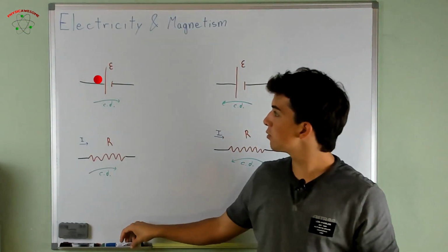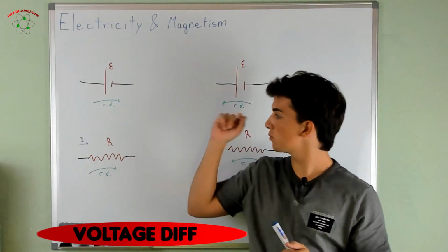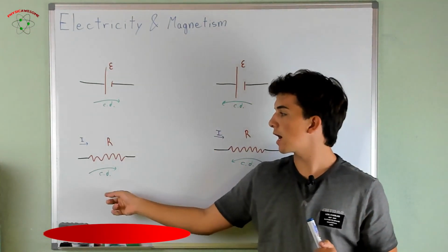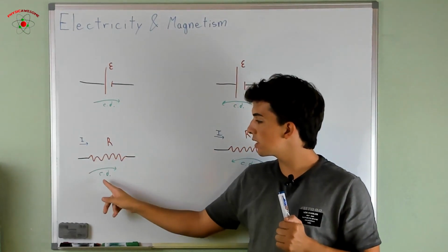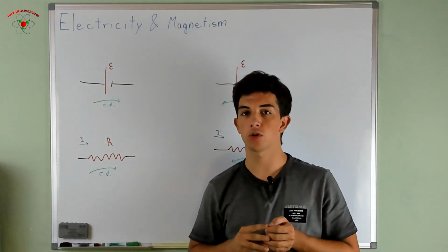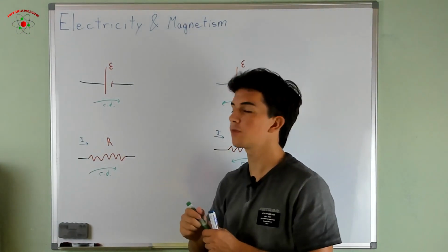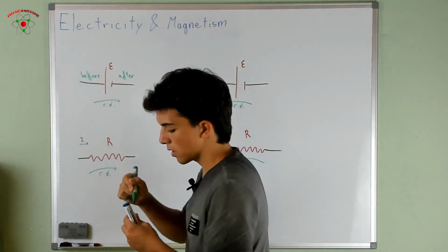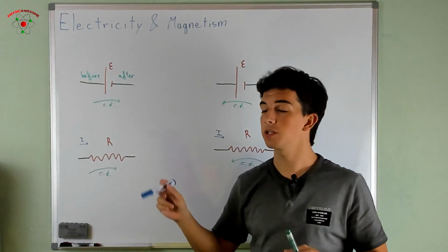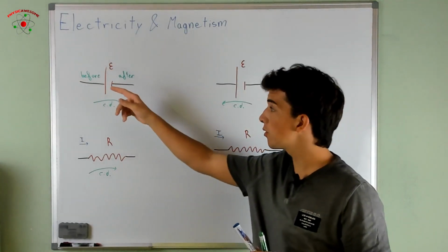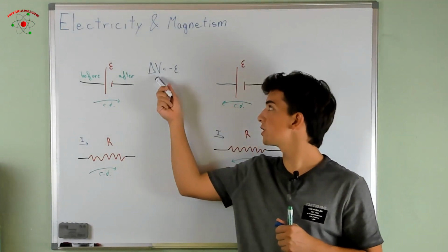Great. Now we're going to explore how the voltage changes across these different situations. We have batteries going with the circulation direction in both directions and resistors, in which what's important is not the resistance in itself, but the circulation direction with respect to the direction of current that we have chosen. In this case, we have that this goes from, and of course, in here the voltage is going to be higher, as that's the positive side, than in here, which is the negative side. Therefore, the voltage is decreasing, which means that the change in voltage is minus epsilon.